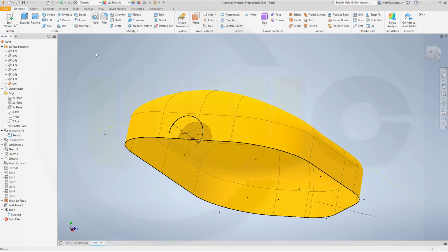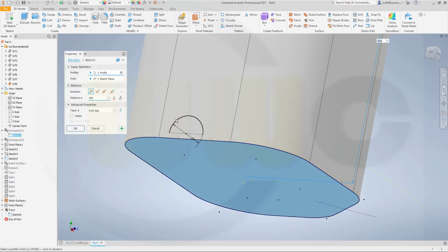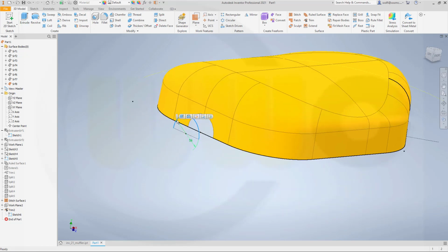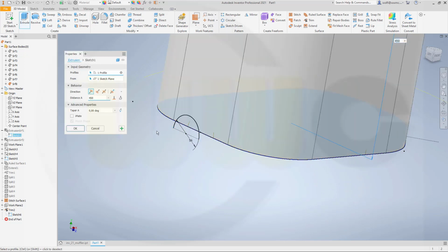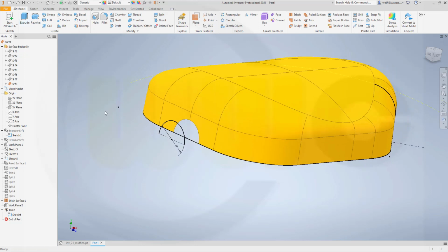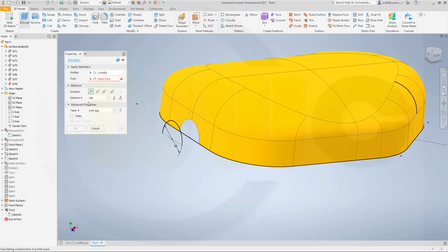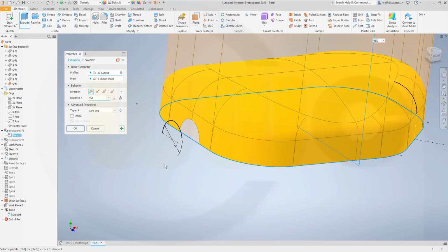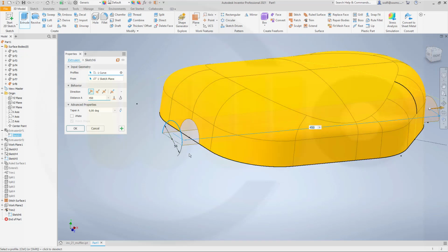Let's make an extrude. No, not with this one, but with that one. And okay, that's sort of crazy. Okay, let's try once more. I want to have an extrude, not with this sketch, but with that sketch. So it always switches to solid. You have to switch to surface, like this, and this should go up to that surface here.